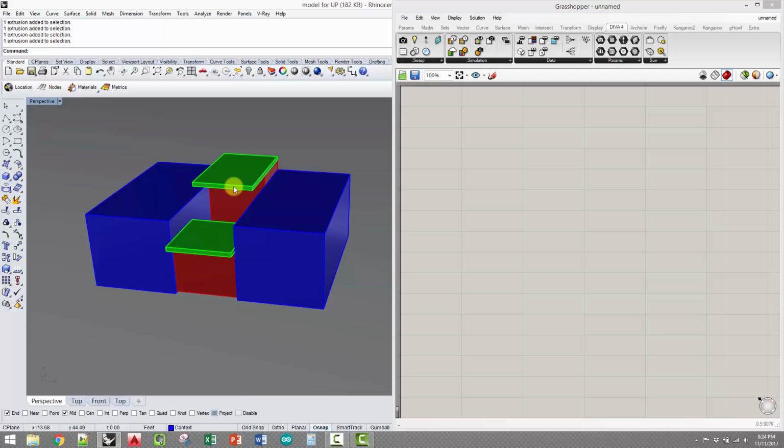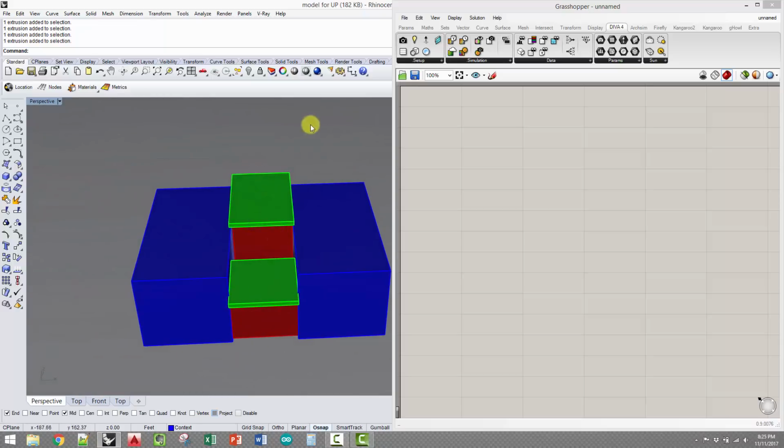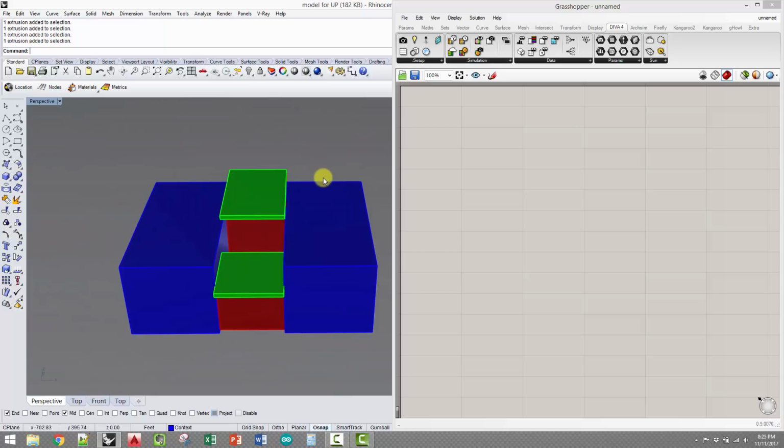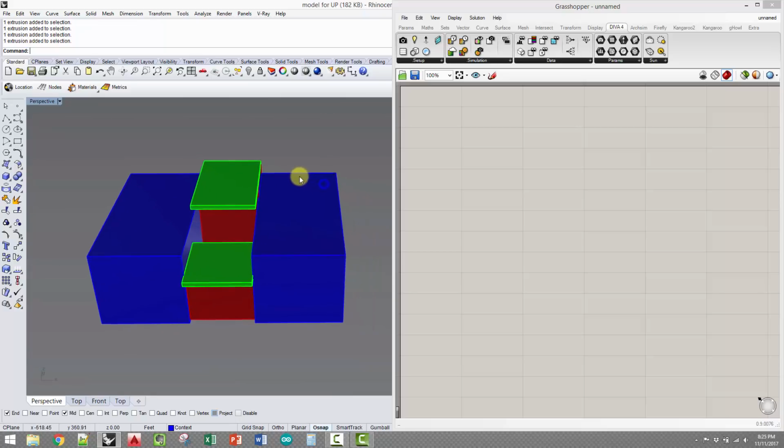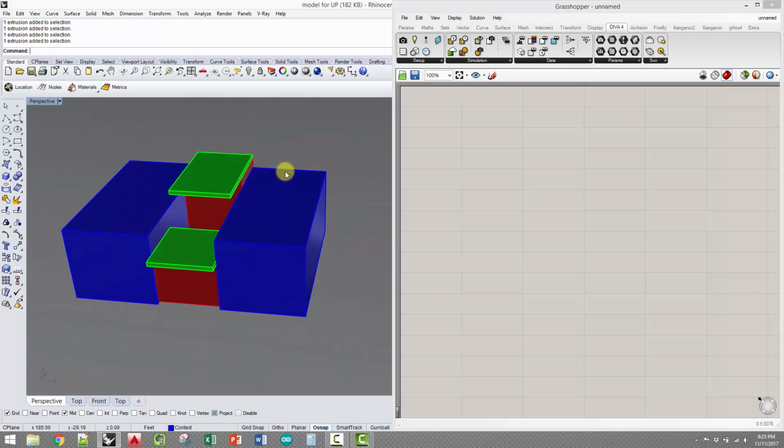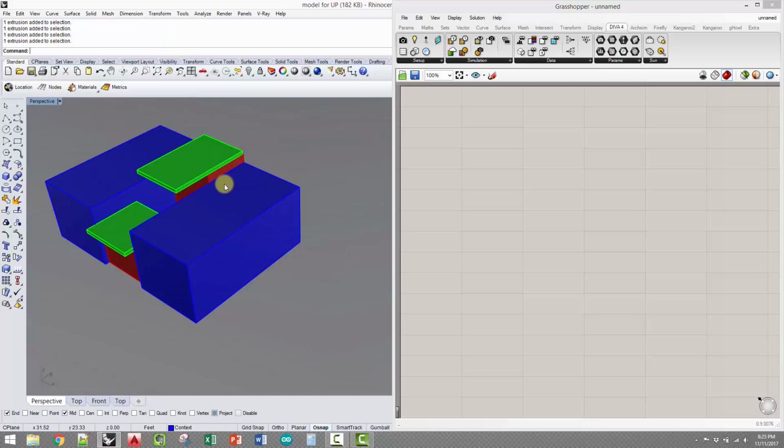And towards that, you really have to be careful to make sure that your building is oriented north to south, or that you've made sure that those parameters are really clear. In this case, yes, south is the bottom and north is the top, okay? But just really make sure that you understand that, because that'll definitely affect the way that the simulation works. And it's really embarrassing on review, when you don't even have the sun in the right place, right?